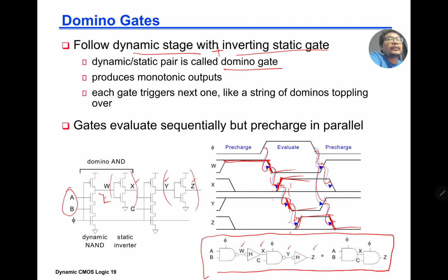One thing we can take from here is that dynamic CMOS is not like regular logic gates. It's not really widely used, so maybe it's not so common, and maybe you have not heard of it. But in dynamic CMOS, you have the pre-charge and evaluate. This is the key thing here. During pre-charge, we always set the output equal to 1, and during evaluate we check whether it is 1 or 0. If it's 1, we don't do anything, so tPLH is 0. If it's 0, then we need to discharge, and that happens only during the evaluate stage.